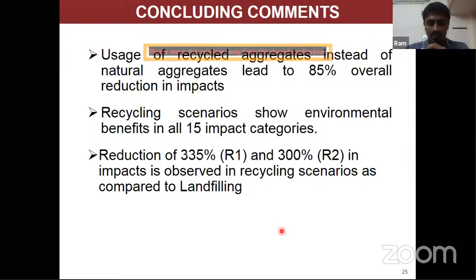Second, the process of converting the bigger chunks of concrete or asphalt using a crusher will be the same. However, the application of the recycled aggregate or the recycled asphalt pavement is slightly different depending upon the properties associated with it. So the philosophy might be the same, but the operation will be different in both production as well as the application of it. I'll leave it at that because maybe another professor, Surinder Singh, and other experts in recycled asphalt pavement might be able to elaborate more on that. Yeah.